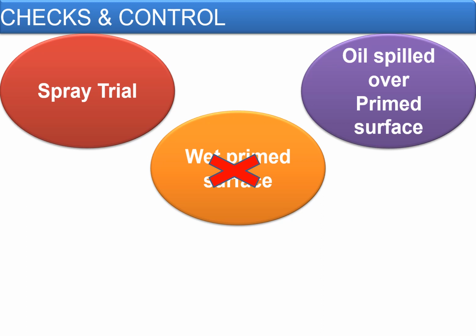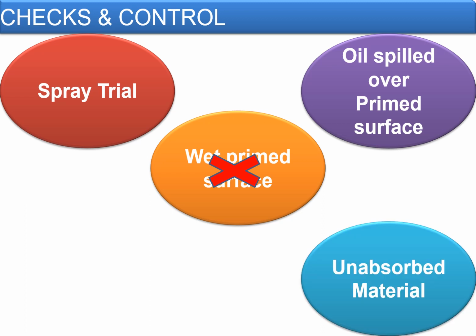Immediately after spraying the tack coat, laying of asphalt should commence. Immediately after spraying of the tack coat, generally within a period of say 1 hour or 1.5 hours, because you need to give sufficient curing time. So it's not immediate, but anyway at least an hour's gap is sufficient to make the tack coat ready to receive the new HMA materials.